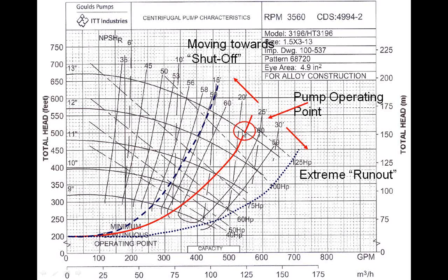As you bring it back here and that control valve opens up, vibration goes away. And the same thing will occur as you come back off and away from BEP and start getting out in this no man's land, I'll call it, out here. When that happens, you'll also experience a lot of vibration coming from over here as that control valve, let's say, opens fully.